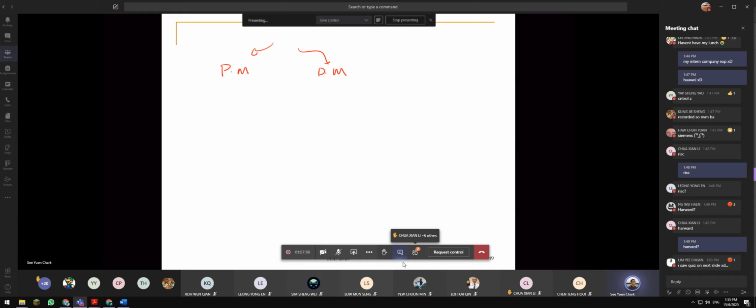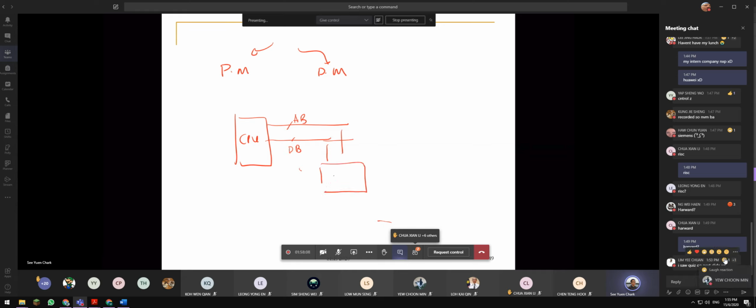For Harvard architecture, the CPU has one address bus and data bus to the program memory, and a separate address bus and data bus for the data memory. More wiring, but faster.